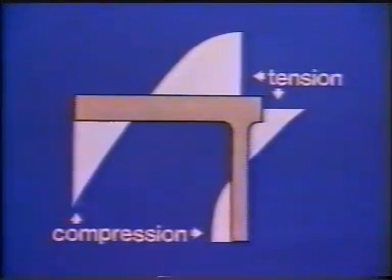As well as the geometrical out of straightness, the column has, in its unloaded state, residual stresses caused by differential cooling and hardening of the steel during the rolling process. The material at the junctions between the web and the flanges cools slowly, resulting in locked-in compressive stresses in the flange tips.